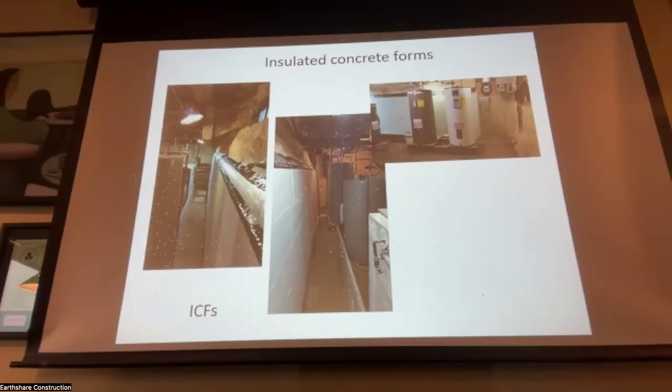What we did was we took nails and nailed up the membrane before we started spraying into the cracks in the stones. Or we laid the plastic along the floor at the base of the wall, and the installer would hold it up and tack it with the spray foam as he went. We would glue it in place. Find the right installer. It doesn't take long to learn. You do the 2 corners, fill the middle. We did a lot of them, so they learned the techniques.